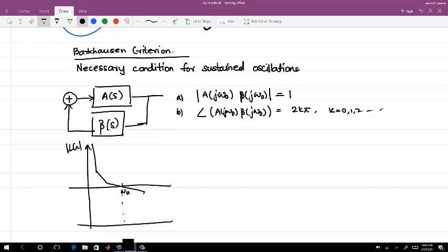Omega u. Where will I start with the phase? This is minus 60 dB per decade, then minus 40, and here minus 20, right? And I can have the system as a very stable system. In this case, what phase do I start with? Minus 270. I will go to minus 180. And since this is a negative feedback, there is another negative 180 degree phase. Okay, it's a PLL system. So in this case, you will start with minus 270, go to minus 180 and something.